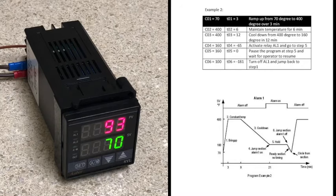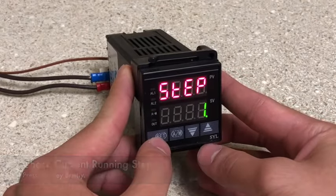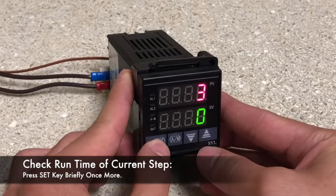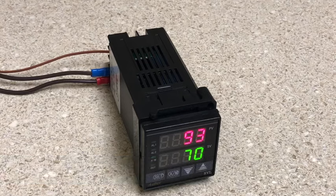So now it's been a while, and I've already checked my program step, and it seems it hasn't run yet. I can check this by pressing the set key once and seeing that it's still in step 1. The reason why is because the set temperature cannot be significantly lower than the ambient temperature. And our ambient temperature here is 90 degrees. So by setting it at 70 degrees, the timer isn't starting.